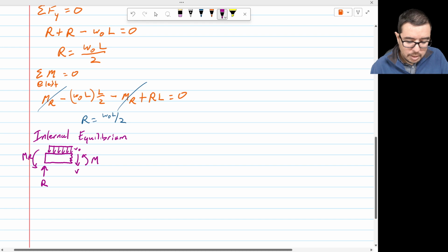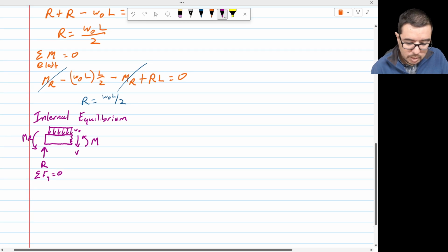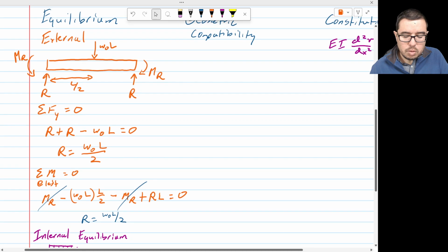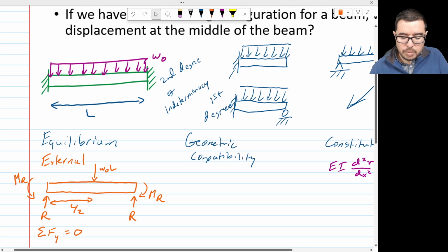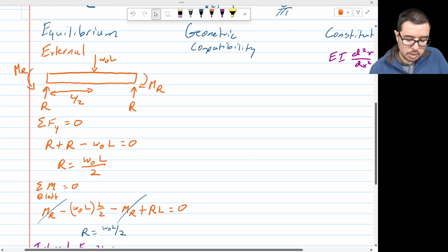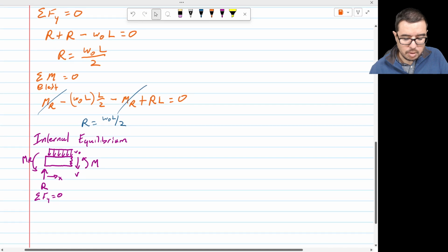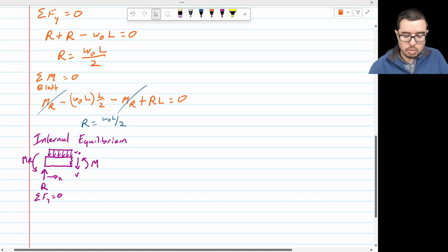The equilibrium for the forces, and this is going to be a parameter x, and there's no additional load. If I go all the way back up here, there's no additional load or concentrated force, coupled moment, or change in the distributed force as we go along this beam. So it's fine to just stick with an x parameter across it, right? I don't need to do an x1 and x2 or anything like that.